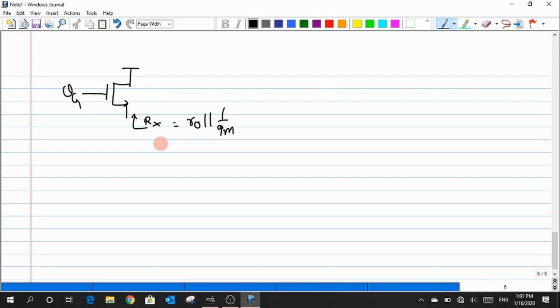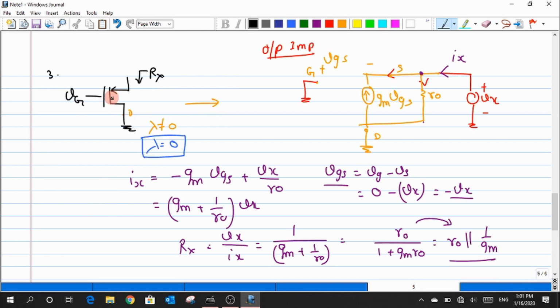Okay, yeah. Now let me mark this as 4, and the fifth circuit would be... I forgot one more thing in the topmost circuit. What happens if the body is connected basically to my ground, or in this case the body is connected to my VDD because it's a PMOS? We didn't address these two issues in this small signal model. So let us try to map this VDD onto the small signal model. So what happens when this body is getting translated to my small signal model?